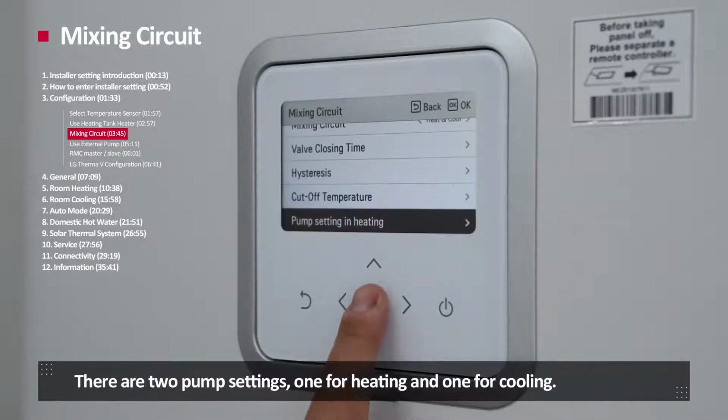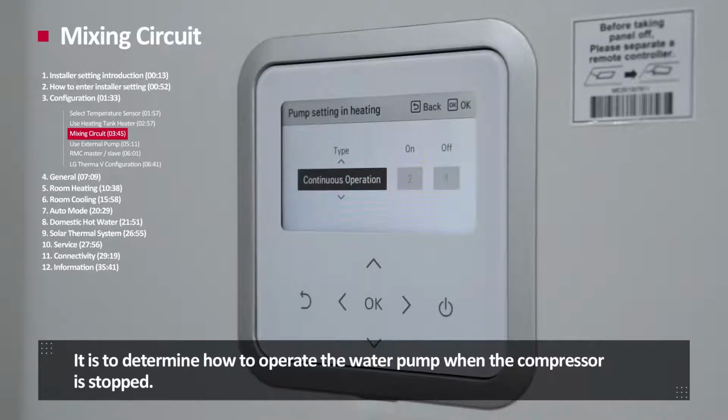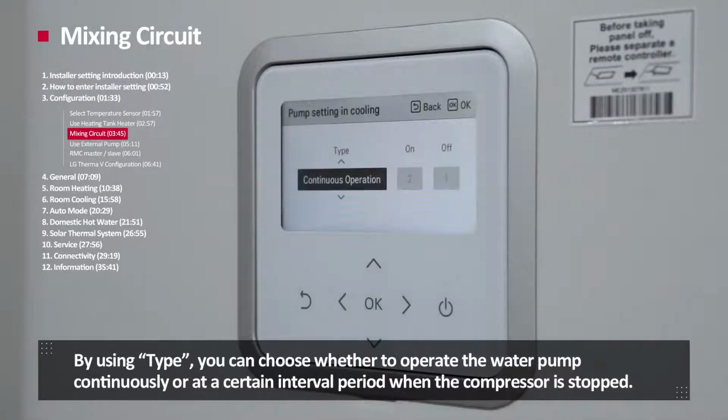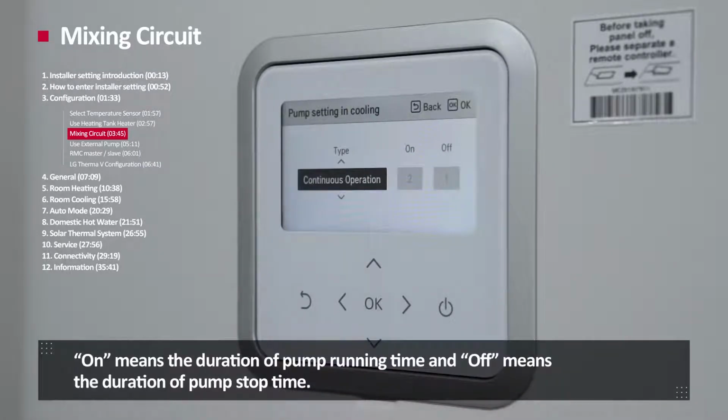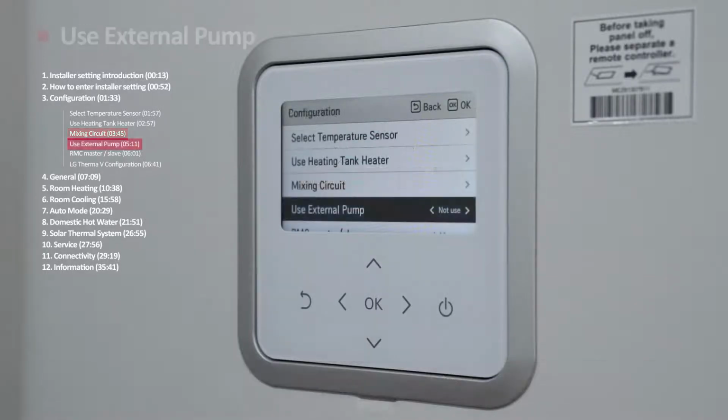There are 2 pump settings, one for heating and one for cooling. It is to determine how to operate the water pump when the compressor is stopped. By using type, you can choose whether to operate the water pump continuously or at a certain interval period when the compressor is stopped. On means the duration of the pump running time, and off means the duration of the pump stop time. It can be selected from 1 to 60 minutes for both on and off.